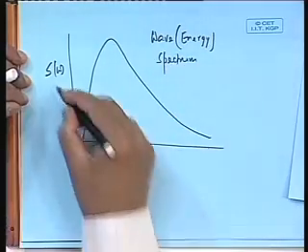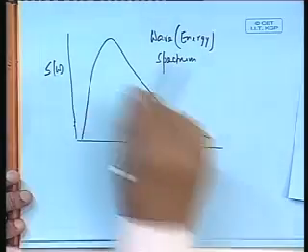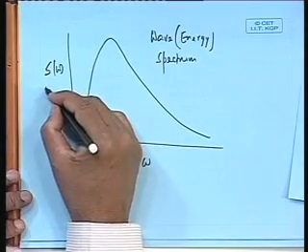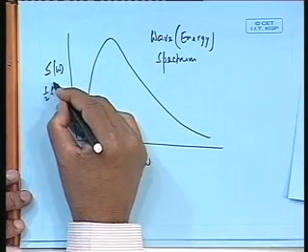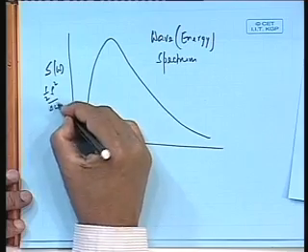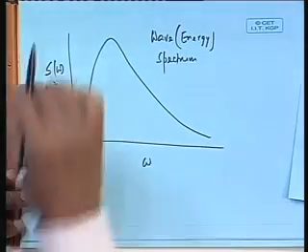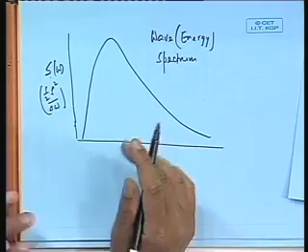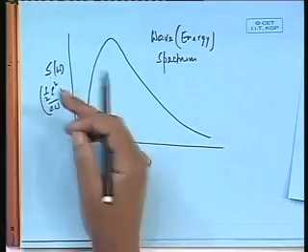So it is called S omega. This is actually proportional to half xi amplitude square by delta omega. This is how this side is, as I said. So this multiplied by rho into g will give you energy per unit surface area. Again, it will have a unit of energy per meter square. We will come to that later on.